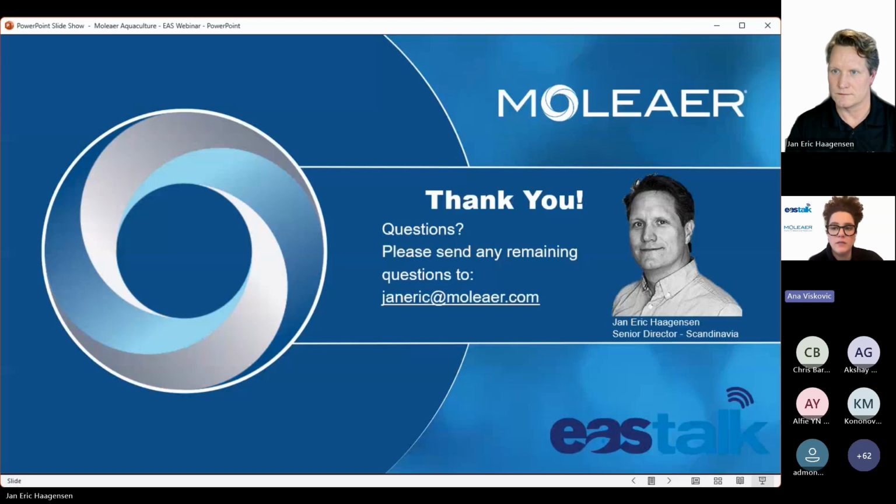The next one is from Jack Jarvis. Is more CO2 stripping required when using nanobubbles compared to oxygenation/aeration systems? Good question. The answer can be both yes and no. If you have a system that is dependent on the oxygenation effect in itself, let's say you have diffuser hoses, and this is a stripping effect, right? These bubbles are going to surface and then you have this aeration. So this process is two-part: it's stripping and it's also oxygenation. If a system is dependent on this and you're only using nanobubbles, where we're very efficiently adding oxygen, but not throwing away oxygen, if you will, then yes, you may need to add a stripping effect. But if you have that from before, no.